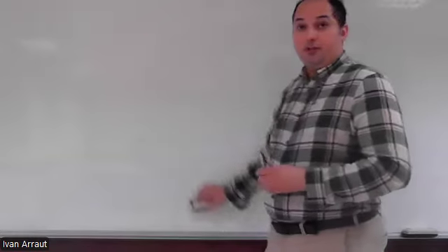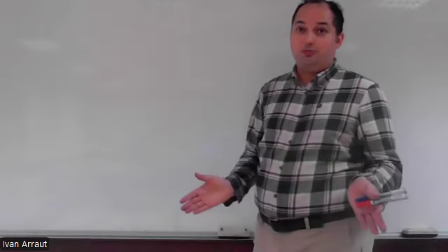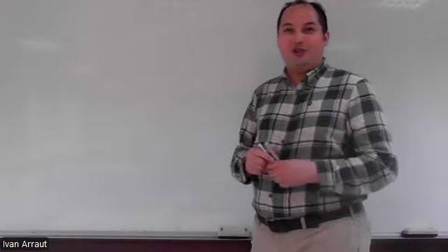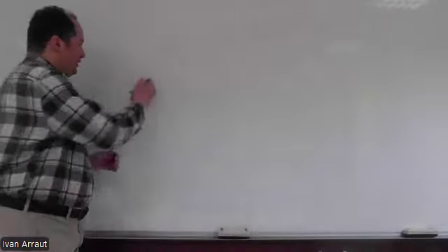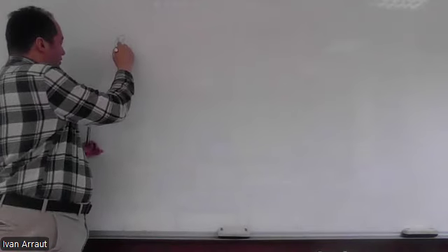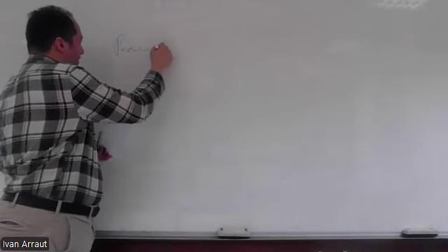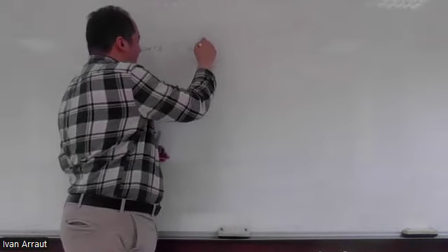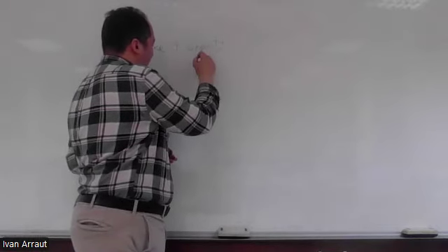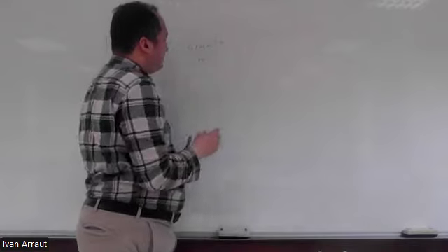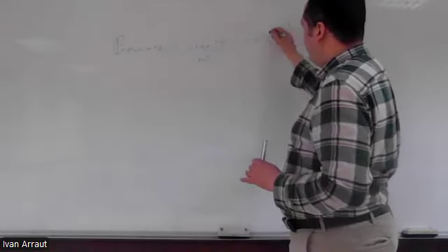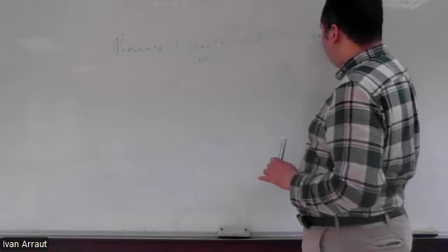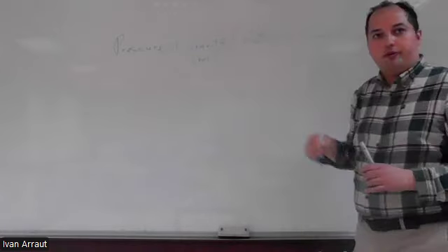with Bernoulli. Bernoulli is conservation of energy. It's an extension of the first law of thermodynamics, actually. But there are some issues. There is an energy due to pressure. There is an energy due to gravity, which is the potential. And there is kinetic energy. This is constant when a fluid is moving.